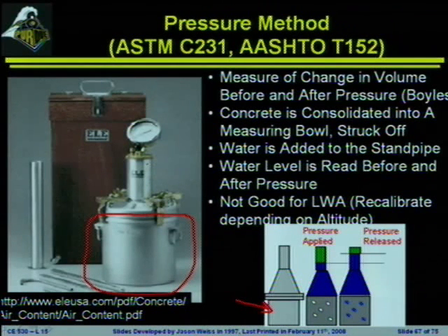The level of water will be measured before and after pressure, and the basic idea is that you can pressurize the water to go into the air-filled spaces, and you'll get an idea of what the difference is between when you've got the pressure applied and the pressure released, and that'll tell you the amount of air in the system.